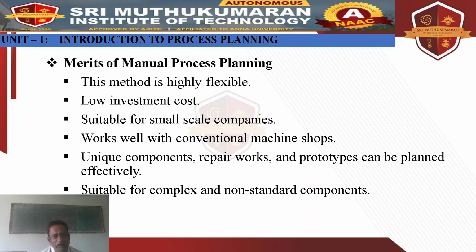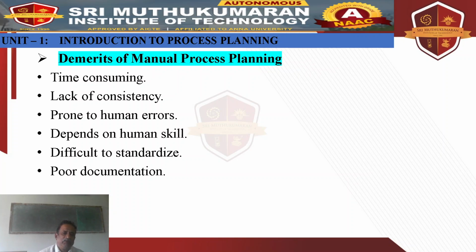So merits of manual process planning. It is very flexible, low investment, suitable for small scale companies, and it works well with conventional machine shops. Also unique components, repair works and prototypes can be planned effectively, and it is suitable for complex and non-standard components. The demerits of manual process planning: it is very time consuming, it lacks consistency,